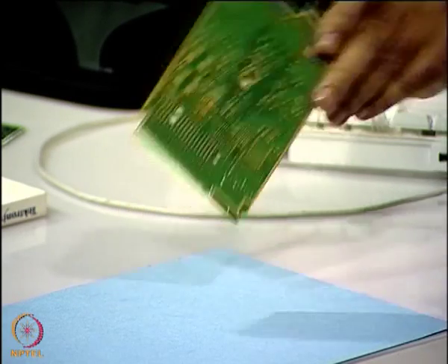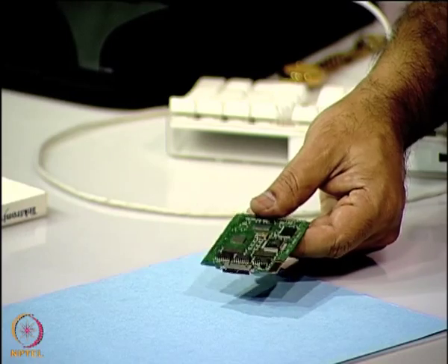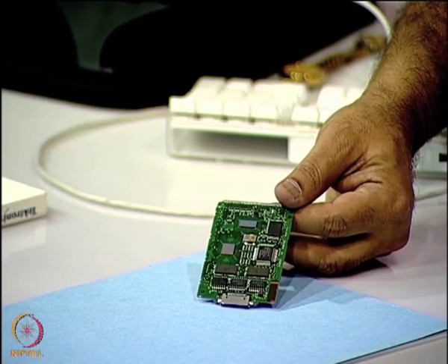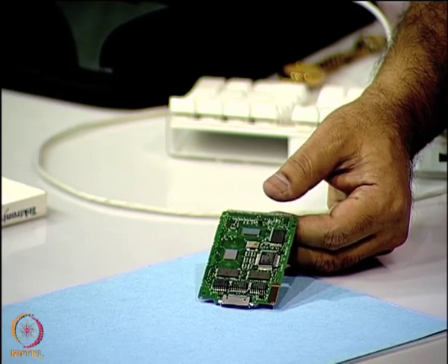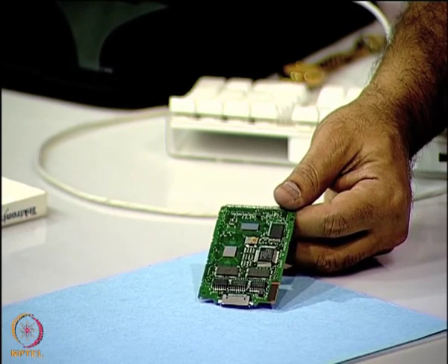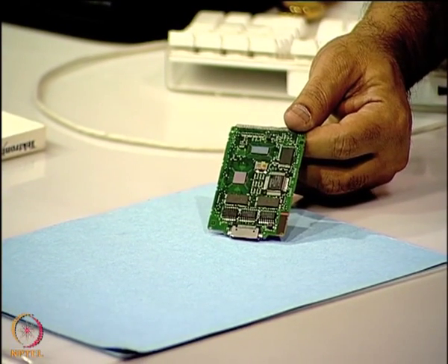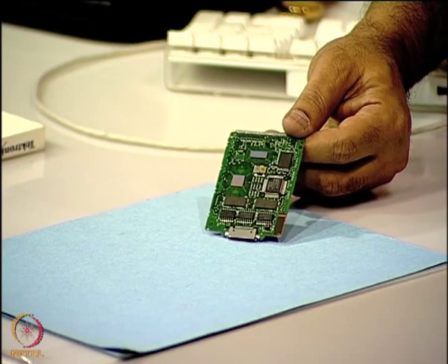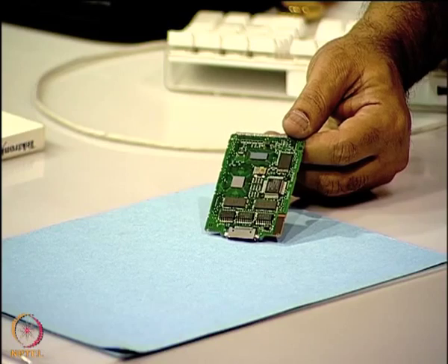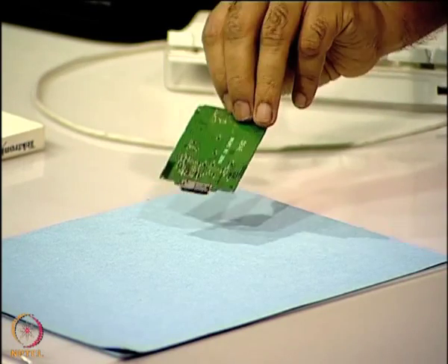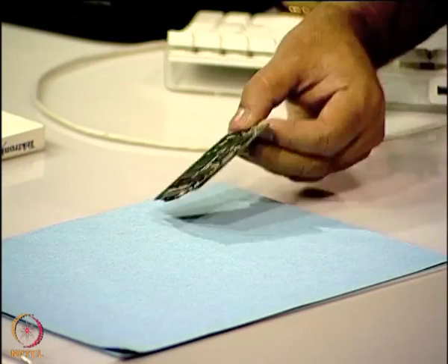interconnect structure. Now, you can also have another kind of high density interconnect structures, as you can see here. This is an 8-layer sequential build up high density interconnect board. You can see advanced packages like a BGA and a flip chip, a lot of QFPs, surface mount resistors have been mounted and both sides have been utilized.